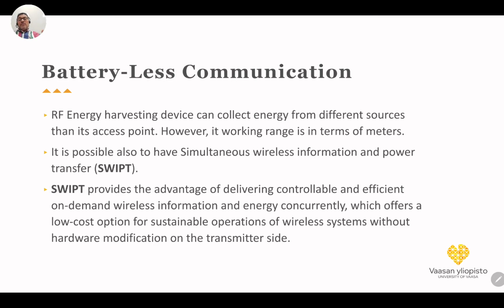It is a little bit different from the inductive based one. NFC or RFID is based on induction, so the transmitter doesn't transmit an electromagnetic wave, but you just close the coil, which makes inductive coupling between the transmitter and the receiver. So the technology is conceptually different, but the operation itself is quite similar.